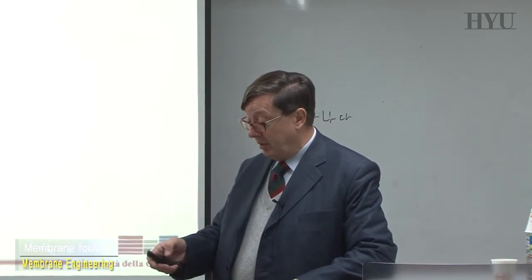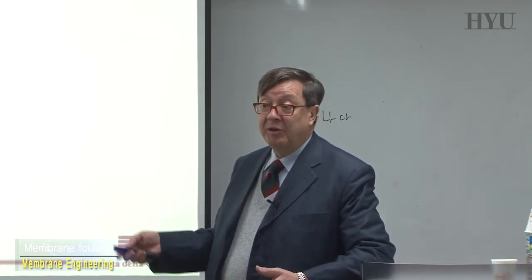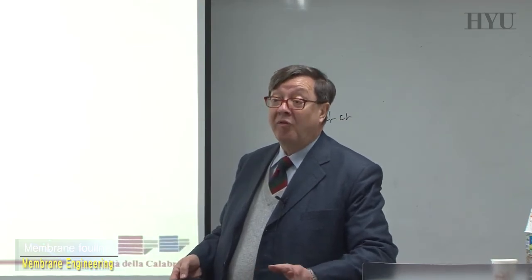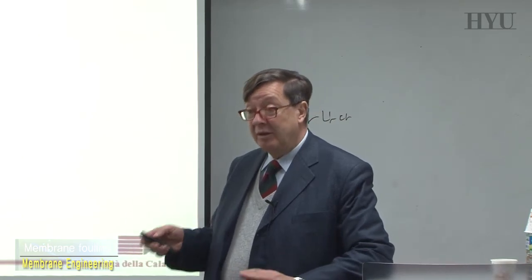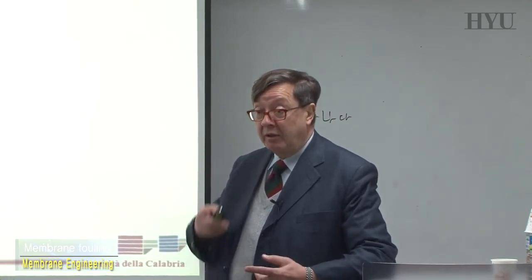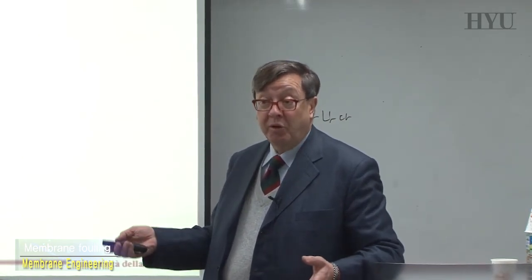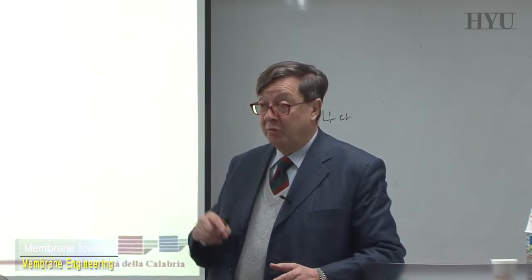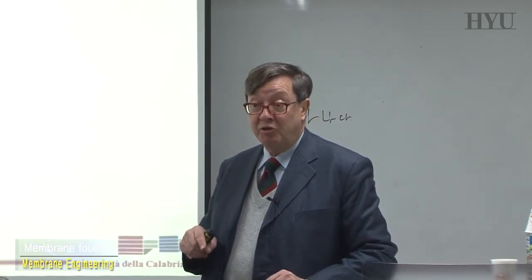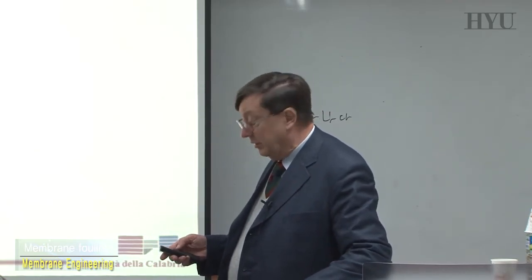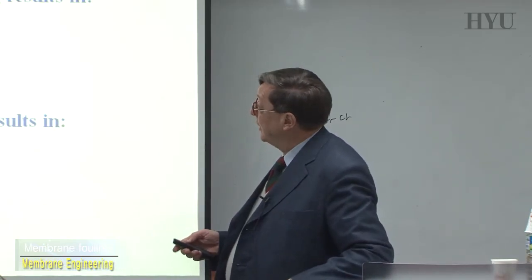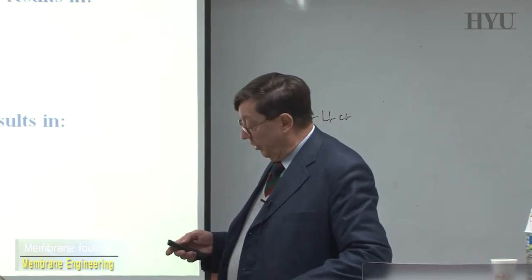If anybody is trying to tell you that you can make a nice operation with membranes with no fouling, don't trust. Fouling is also present, and you have to learn how to handle and how to solve the problems. If you assume there is no problems, that can be dangerous, because the problem will appear. So we have to consider this is what we call intrinsic aspect of any membrane operation.